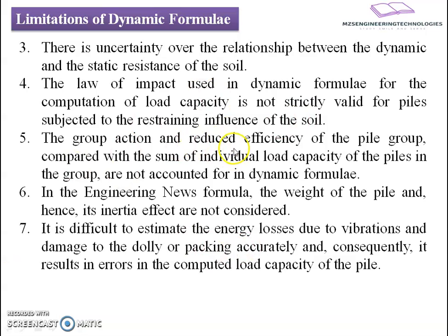The group action and reduced efficiency of the pile group, compared with the sum of the individual load capacities of the piles in the group, are not accounted for in the dynamic formula. Now it's very clear that it can be applied for a single pile and the estimation is very good for that. But when a group of piles is going to have group action for the load applied on it, this action is not clearly represented by the dynamic formulation.